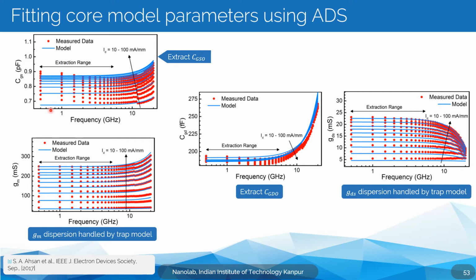And this bias dependence, which is the trend you see with different biases, is captured automatically once you have a good DC fit. So this really makes ASM a turnkey solution: you just have to get a good DC fit, and these bias dependent parts are automatically taken care of. Then all you have to do is tune the overlap capacitances so you get these levels right.